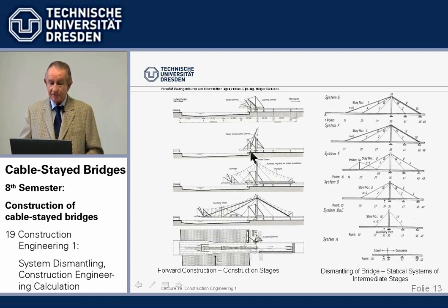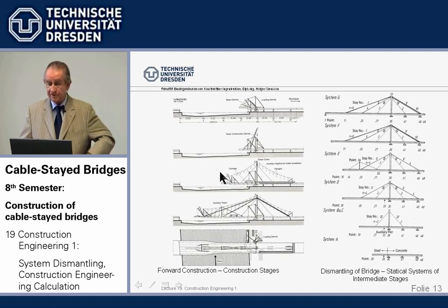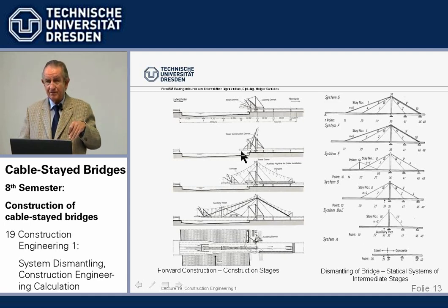And we need, for the first element, a little auxiliary pier before we reach the first cable. And then we use a derrick for lifting up the elements. And here they had a special method, a little complicated, to install the stay cables with a high line. That is a suspension bridge cable, one would say, a high line, from which the new cable was supported.